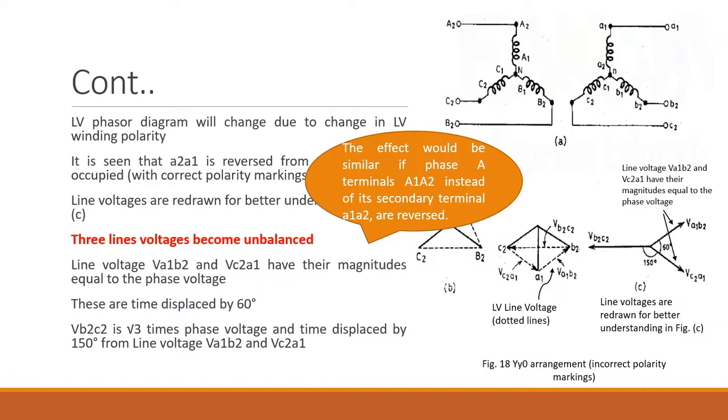Okay, you might have some question, because earlier what we did is just we have changed the terminals on the LV side and kept fixed the HV side terminal for phase A. You can reverse it, keep the LV side terminal the same. If wrong polarity is on the HV side, the same result will be there. Nothing would be changed. On a similar line, if for any other phase this is happening, yes, the result would be on a similar line.